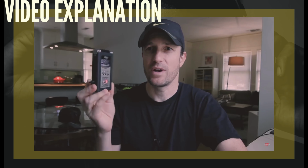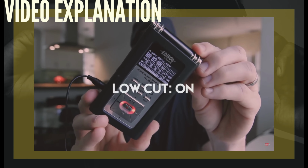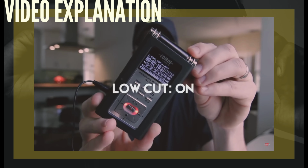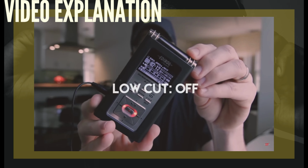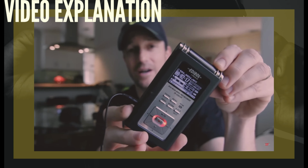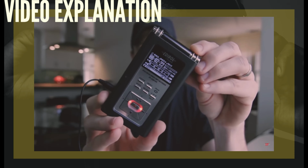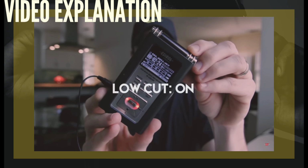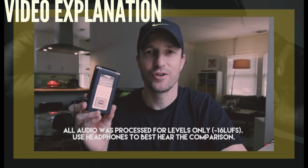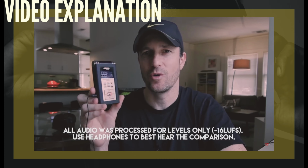When we enable this, watch what happens. You can see that bouncing, and when we turn it on, gone. Turn it off. And now you're picking up the air conditioning, essentially, that low end rumble of the air conditioner. And we'll turn it back on. So if you have a low cut filter, that's one thing it can do for you. You can improve that signal to noise ratio by knocking out that low end rumble.